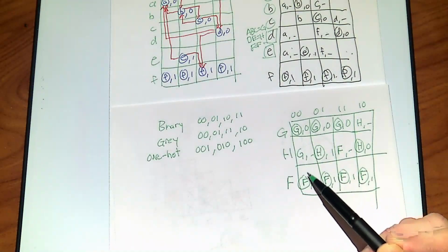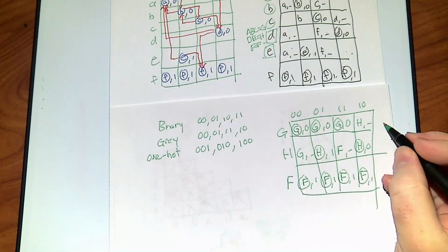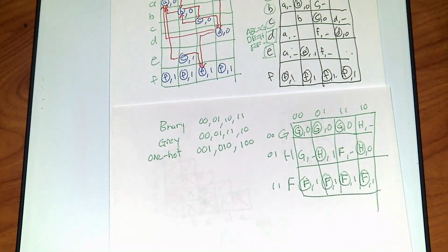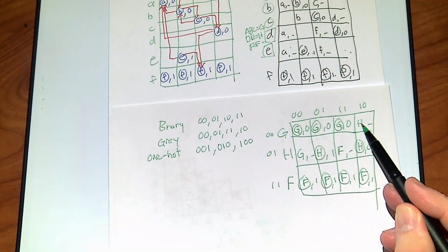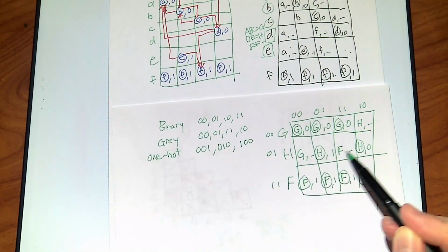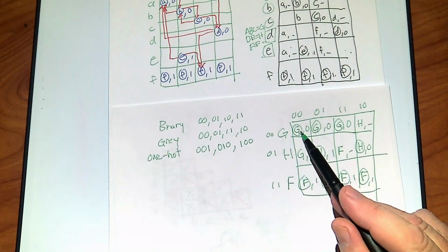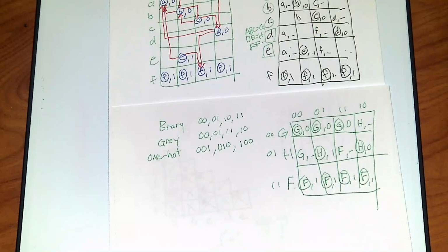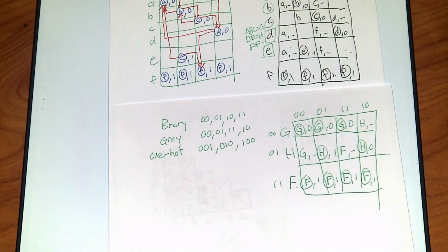I can make this 0, 0, 0, 1, I can make this one 1, 1. In this case, that'll actually work quite nicely, right? Because in this case, I only go from 0, 0 to 0, 1. Here I can go from 0, 1 back to 0, 0 or to 1, 1, and I never leave 1, 1. But what if one of these states went back to G? We got a race.